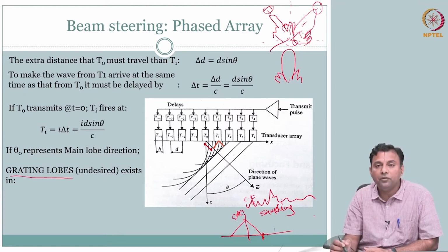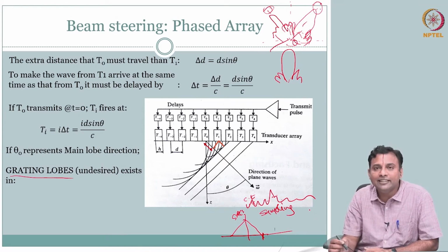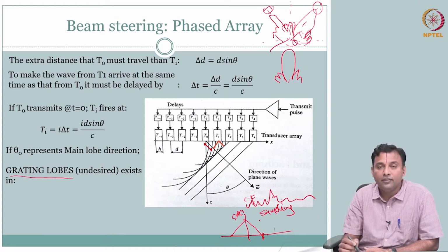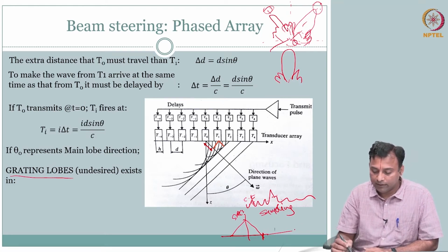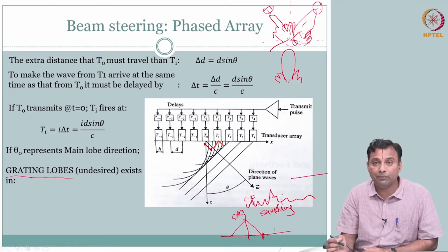After you do sampling, how do they explain aliasing? Oh, you have a spectra, but now when you sample, the Fourier transform or the frequency domain is going to have copies of this, right? So you want to sample so that, for the sake of clarity, let me not draw here another spectra. Now this is of the discrete samples.